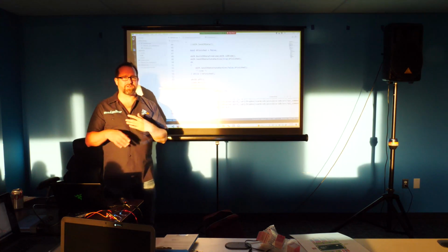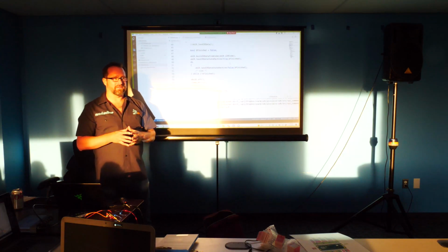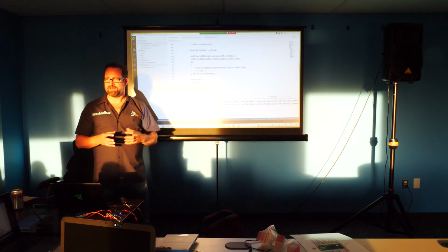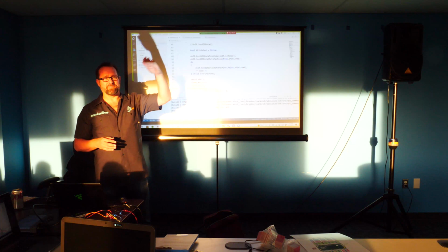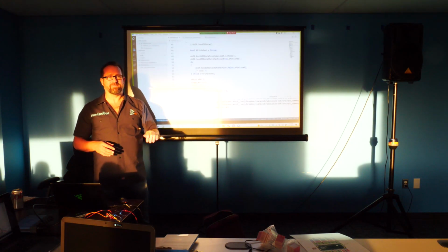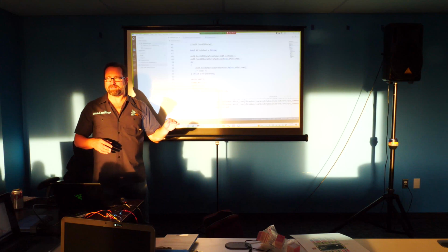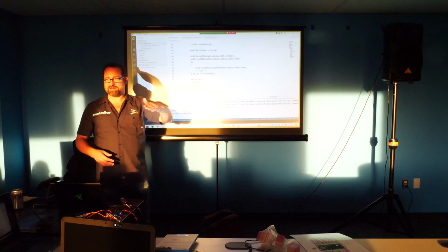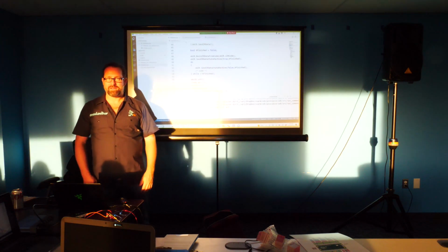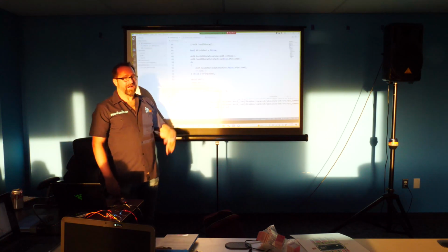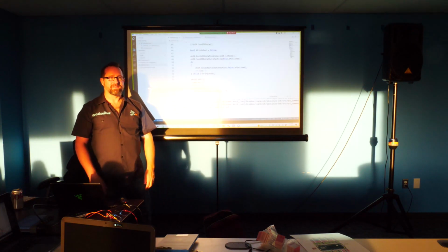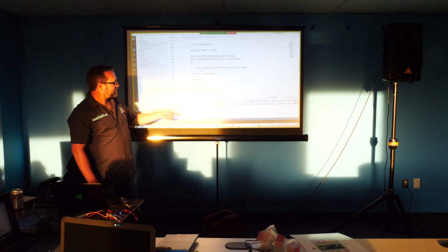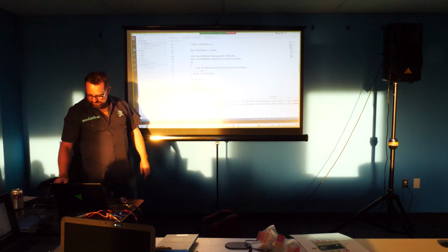There are different ways to write your code. A lot of code designs or examples are blocking, which means you have to finish one step before you move to the next, which is incredibly limiting for any complicated project. If you look at a lot of the Python stuff, it's like, I'm going to do this until it's done. You saw that the IR message took about 70 milliseconds, so that means you can't do anything for that whole 70 milliseconds. We're going to talk a little bit about that. And then we just toggle the LED, and that's that.